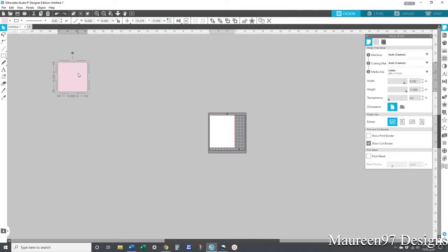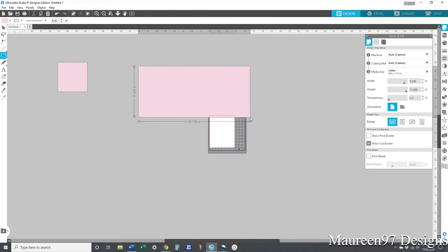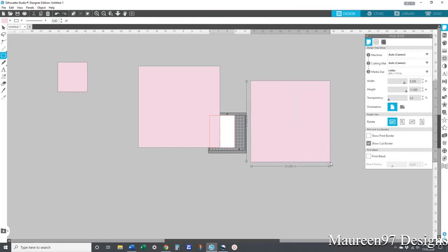There are several ways you can do it. You can draw all your squares, and the other thing you can do is when you're drawing your rectangle, you can constrict it to be a square by just hitting the shift key. A little tip is to let go of your mouse button first before your shift key so that you'll keep it as a square, because if you let go of the shift first, it's going to go back to being a rectangle.